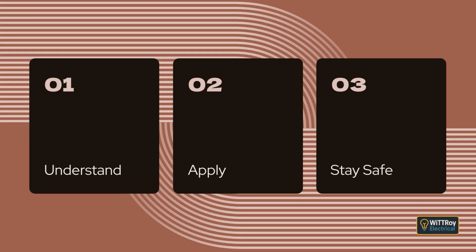Clause 2.7.2, Protection by insulation or separation. Clause 2.7.2 covers how insulation or physical separation can prevent dangerous overvoltage effects between parts of the installation. This includes using adequate insulation or screening for conductors, providing insulation or screening between transformer windings operating at different voltages, and ensuring that if a transformer fault occurs, the protective earthing system causes the supply to disconnect. The key idea is that physical barriers or insulating materials help stop high-voltage faults from affecting low-voltage circuits.